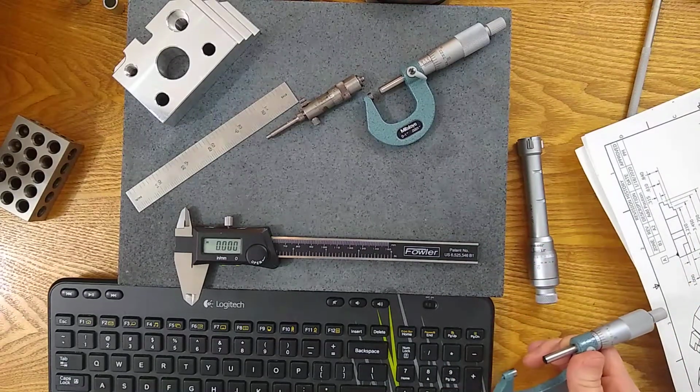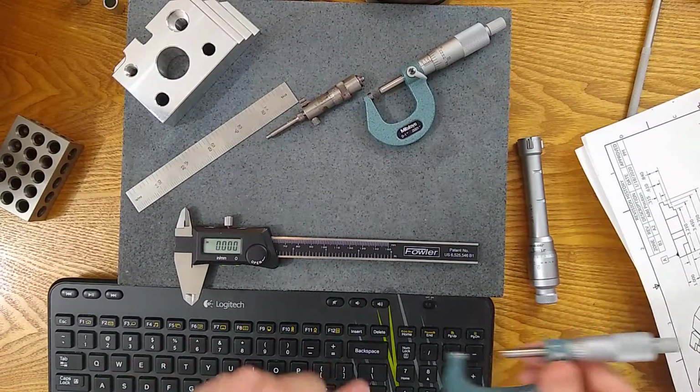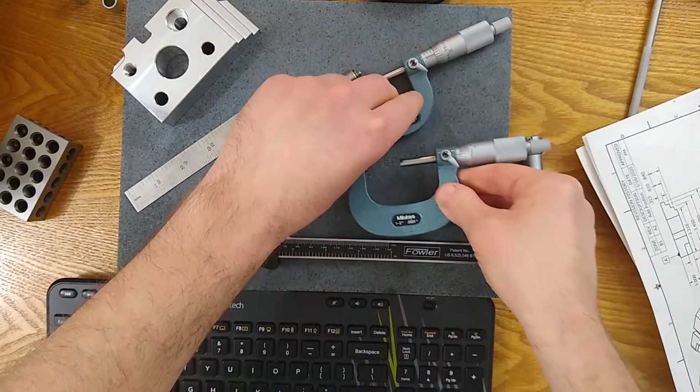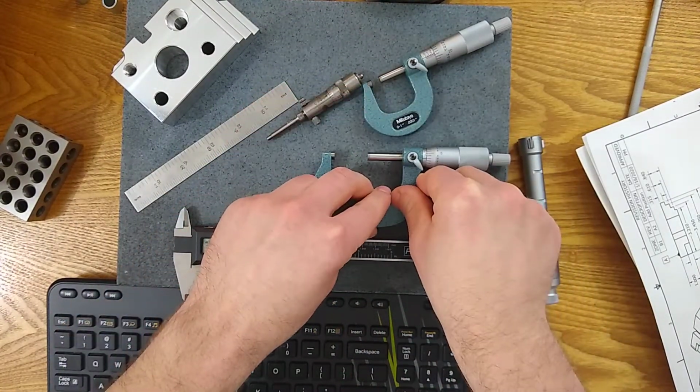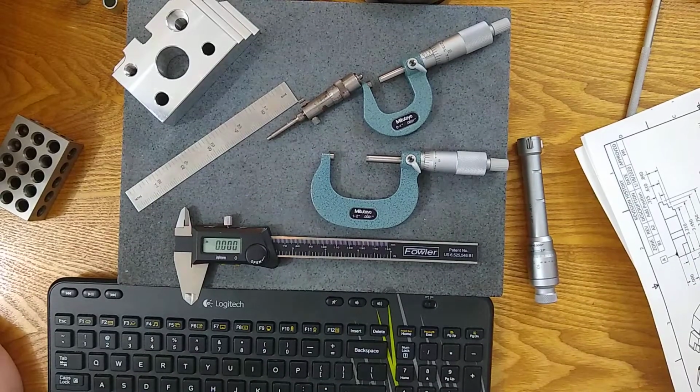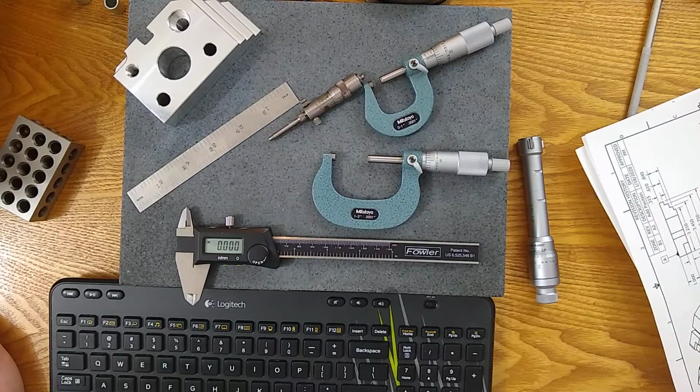So that's a few gauges. We will move on. I will show you just a few more. So I have all the micrometers on one slide here. The most common micrometers, I should say. So, bore micrometers, resolution is typically around 2 10,000ths or 2.5 10,000ths.